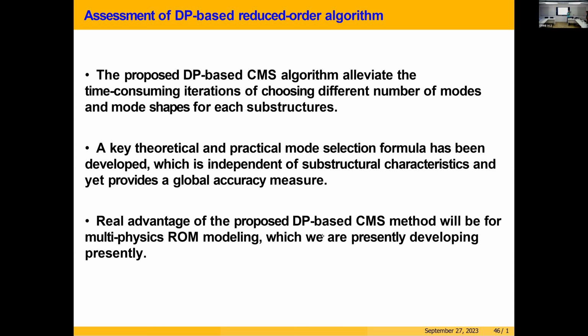In my case, I satisfy an acceleration constraint and a displacement constraint. Therefore, I satisfy two linearly independent variable constraints. In the quasi-static case, if the loads are not equilibrated, you should equilibrate them in order to get a unique solution, right? In the quasi-static problem, it's very important that you get what we call the fundamental solution.